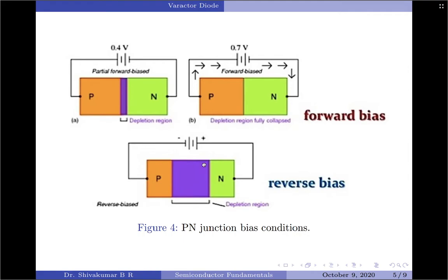So, by now you must have observed the similarities between the capacitor and the diode in reverse bias. The depletion layer in the diode is similar to the dielectric medium in a capacitor, which acts as an insulator and prevents the flow of charge carriers from one side to the other. So, when reverse bias voltage is applied across the diode, respective charge carriers accumulate on either side of the depletion layer. This makes the diode acquire some capacitance, and it is termed as the junction capacitance.